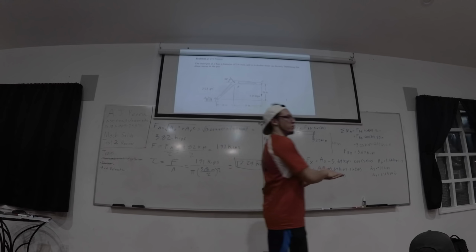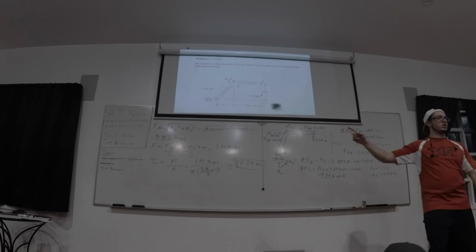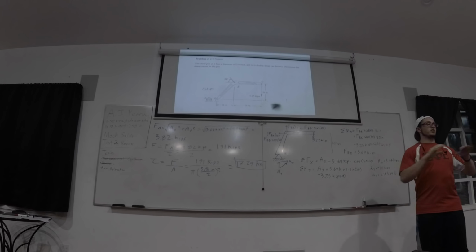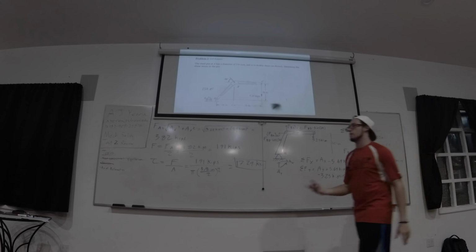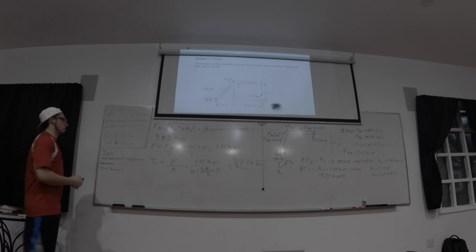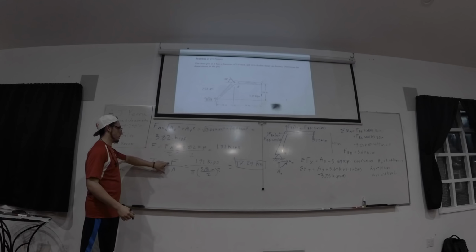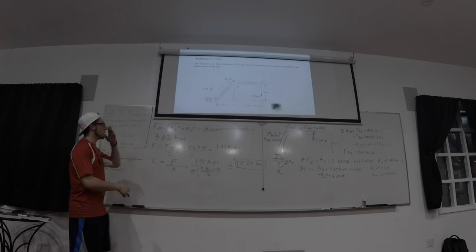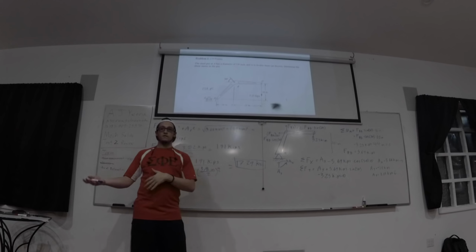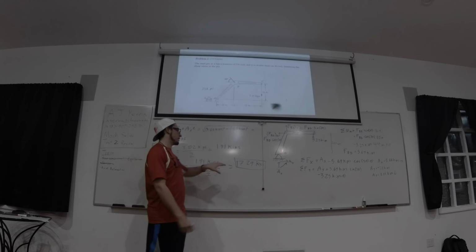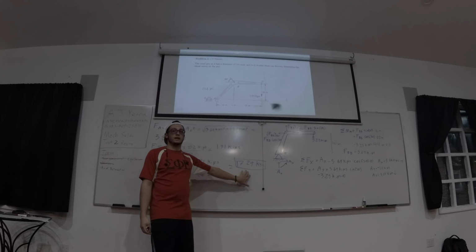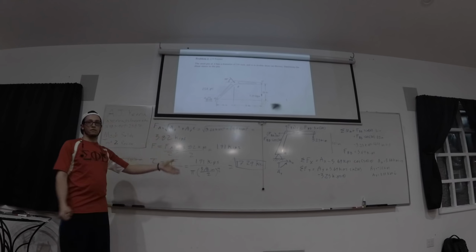Okay, guys, bring it in. One last thing that I forgot I want to touch on for stress before we move on to axial deformation: if the question brings up factor of safety, it might not. Factor of safety is used for design problems where you have some limiting difference from the maximum allowable force. Let's say the problem was phrased differently. They gave you different knowns and asked you to solve for different unknowns, and they told you the maximum allowable stress in the pin is 17.29 KSI, and to solve back for the force maybe.